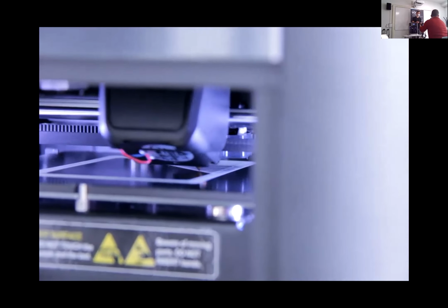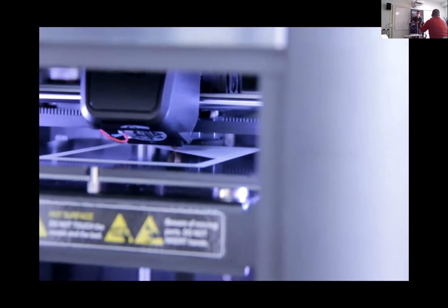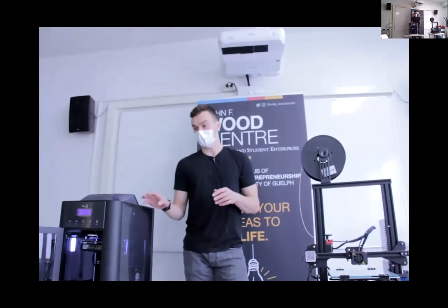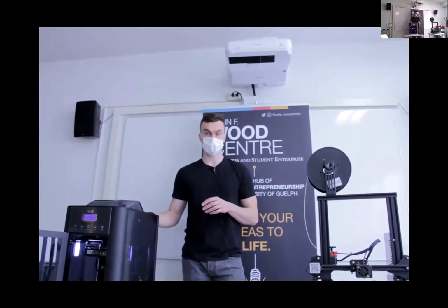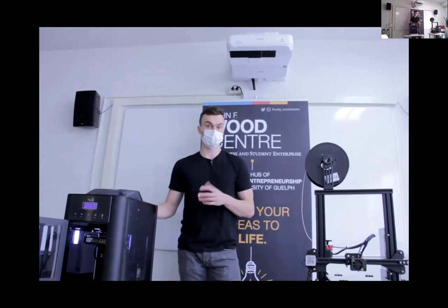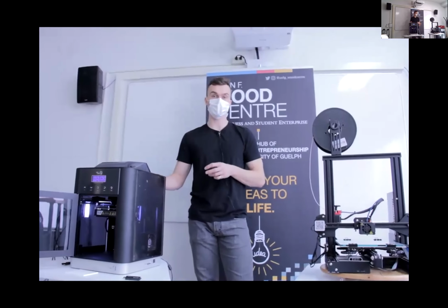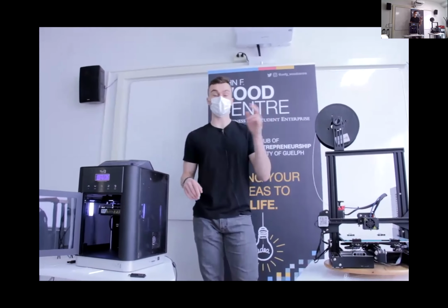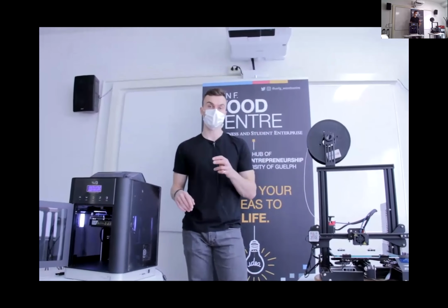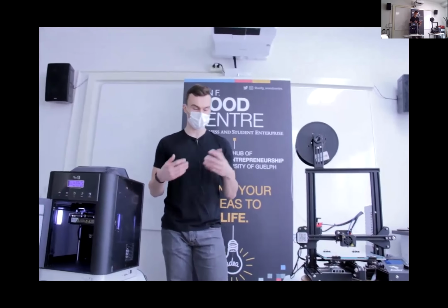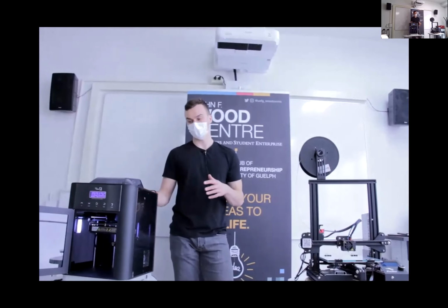So if you had one small thing to print, but you actually wanted 5 of them, you could just import that same CAD file into your slicer 5 times, slice the 5 small objects together, and load that sliced file onto the printer, and it'll do multiple ones at a time. So that's how you would handle trying to print more than one thing at once. Just import more than one file into your slicer at the same time, and then slice them together, and then they'll all print together.